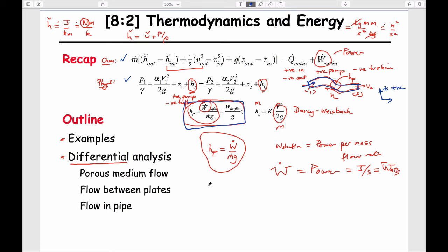I guess the other one is the conversion to torque. So what is it? Shaft work is equal to torque times angular rotational velocity. I think that's power, right? Power is equal to torque times velocity. Yes, that is right. So torque is a force times a lever arm, so Newton meters, and this is a rate, so Newton meters per second, which are joules per second, which are watts. Okay, so those are the three relationships that you need here.